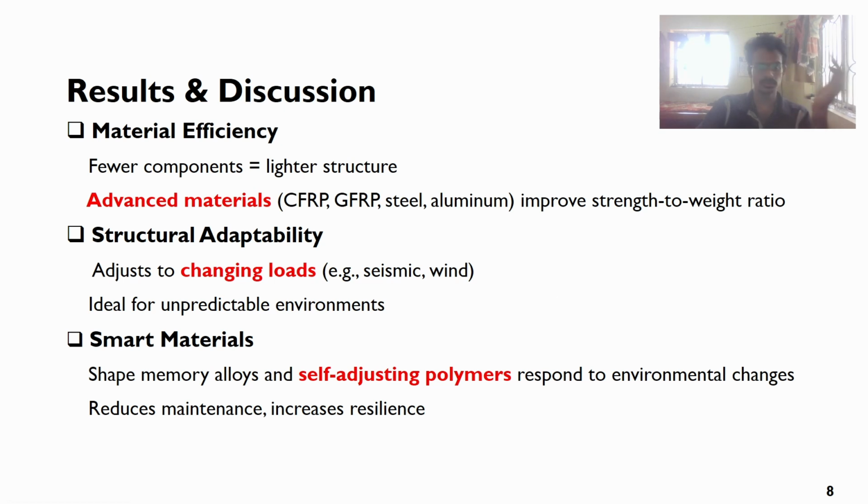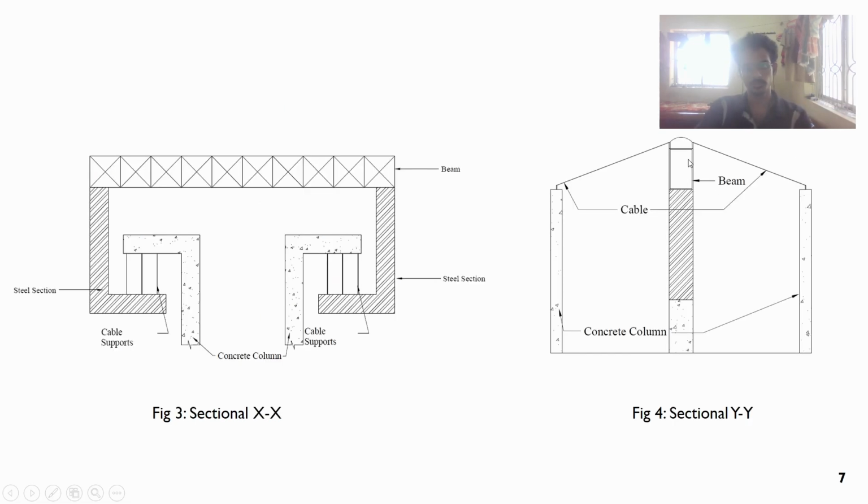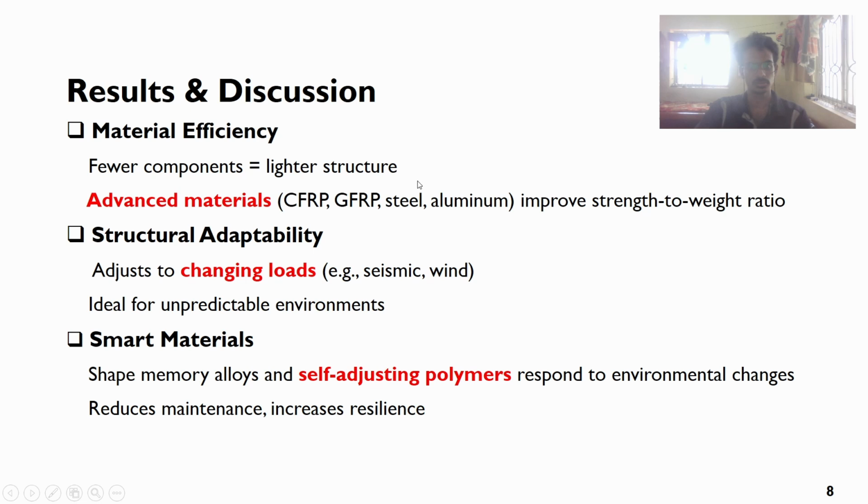As what I have seen right now, to the top, if you're going to use a light material, we can reduce the material components, but due to the changing loads, the dynamic loads, it can become unpredictable, and we need to address stability. The point is, people say that the tensegrity concept is not stable, it moves around, and when there is a wind load or seismic load, because it is a dynamic load, there is a chance of wobbling.